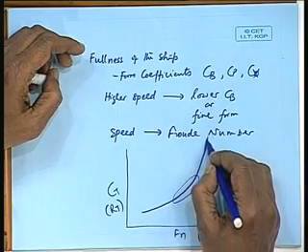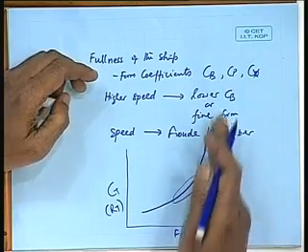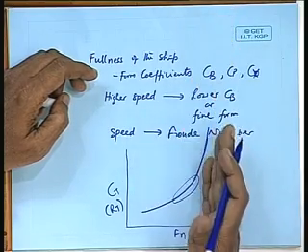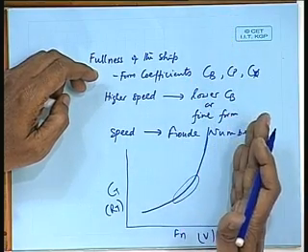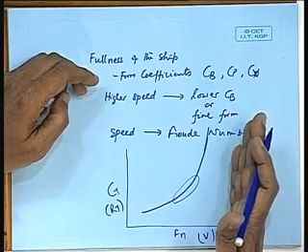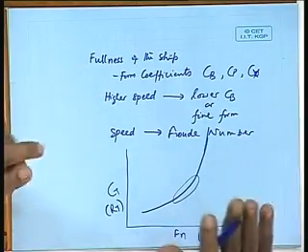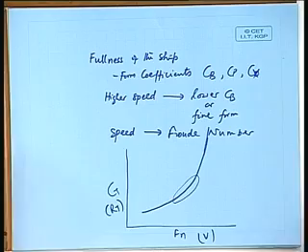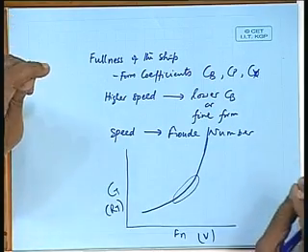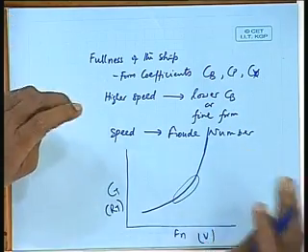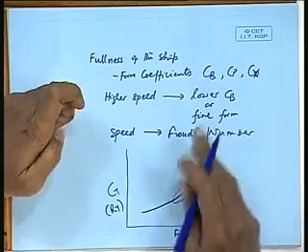Anything more than this, the power consumption will go up tremendously without any appreciable addition of speed. So, every ship will have an optimum speed, and if you reduce in scale, that optimum speed will come down based on Froude similarity. You cannot just go on adding power and say the speed will go on increasing, that does not happen.